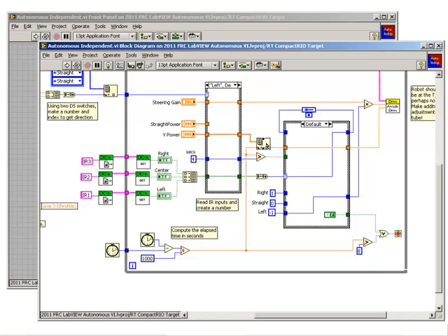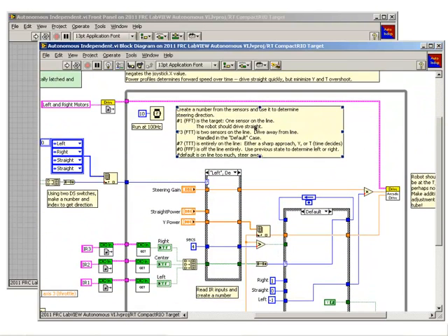The third thing that the elapsed time will do is to check to see whether the robot is on the T at the end of the path, or at the split in the Y. To understand how it does this, we need to look at the second case structure. The outputs of the 3 infrared sensors will determine which cases run in this case structure. The default case is if the right and center infrared sensors are on the line, and so the Boolean array is converted to the number 3.